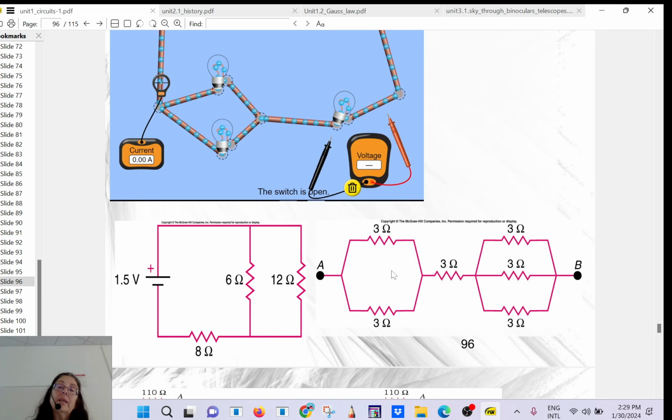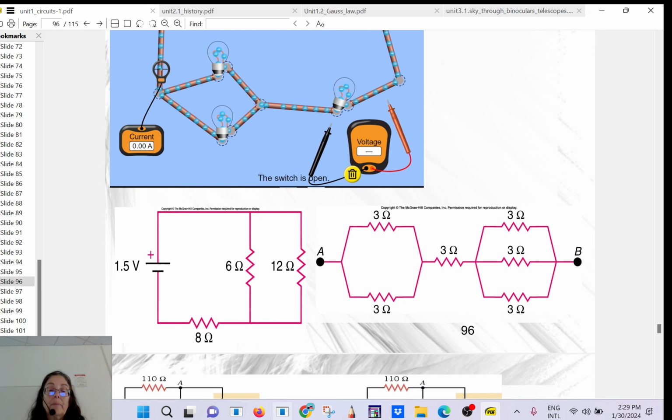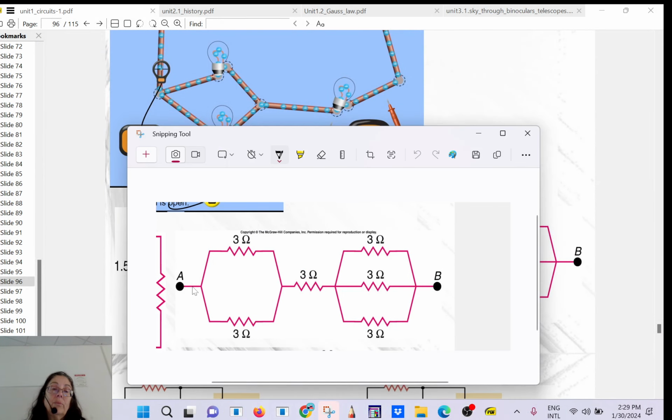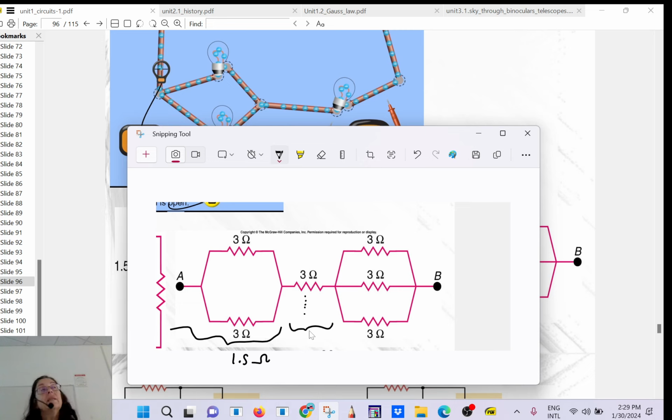Okay, so let's do one thing in our head. Find the equivalent resistance. Always start with the parallel. So you see you have, boom, boom, two branches coming back and then three branches. So this one, what do you think the resistance is? 3 and 3 in parallel. 1.5, very good. And you remember when we did the computation in arithmetic, you bring it down, that's going to be 3. And then 3, 3 and 3, that's going to be 1.